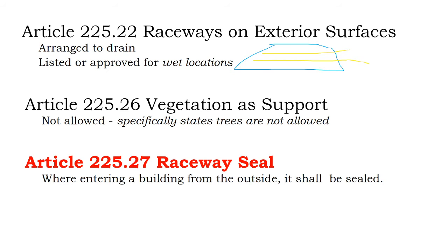If you're depending on your cable management system, if you're putting the cable inside a U channel where there's a little trough that these things make, you have to make sure that trough doesn't fill up with water. So you're going to have to modify your solar rail and drill holes throughout it so that the water drains out rather than pools in. Not all rail is the same.